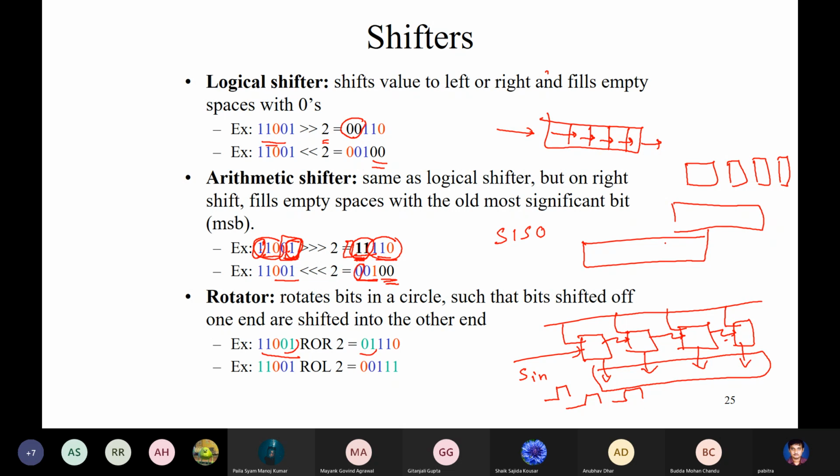You have loaded all the data in parallel, but how do you serially read them out? Suppose I have parallelly loaded 1 0 0 1. If I need a serial out, I would have 1, then 0 0, then 1, like this. How would I get that output? What kind of additional logic or control line would I need?